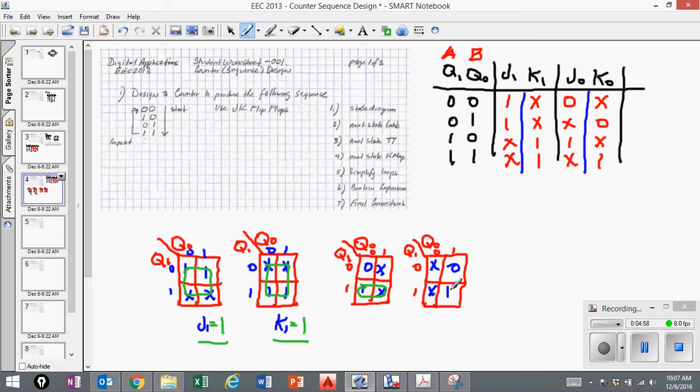Same thing here. This is 1 alone, and I can write this as a Boolean expression. However, I have an x next to it, so I'll make that x a 1 and make a bigger circle. So now I'm able to reduce the output. Remember, bigger circles create smaller outputs. So it seems like these two columns cancel Q0 and leave me with Q1 as a high.